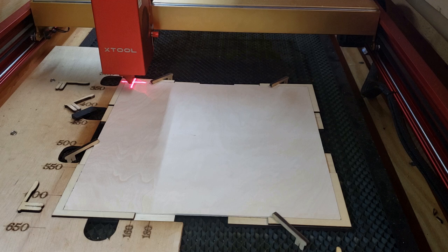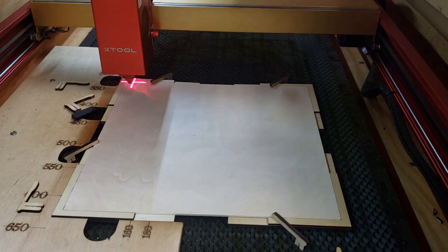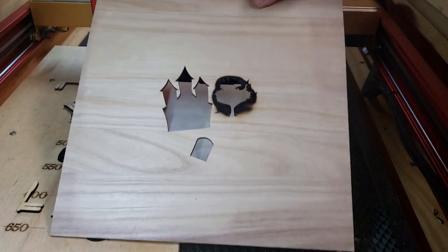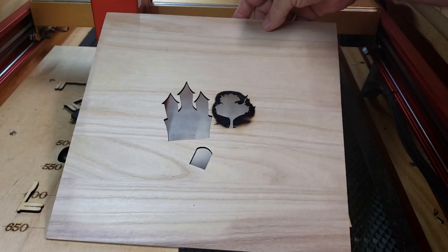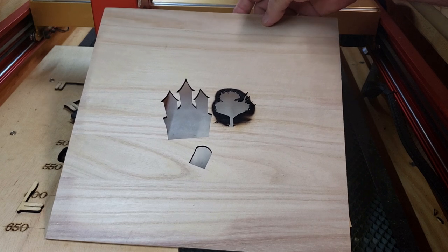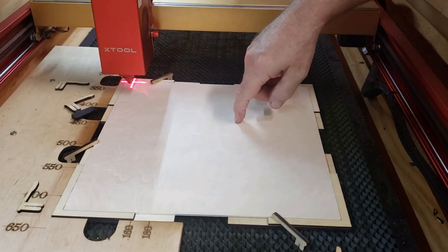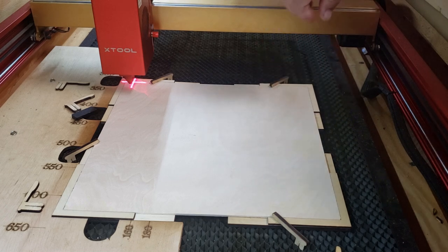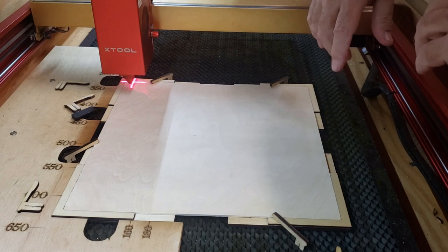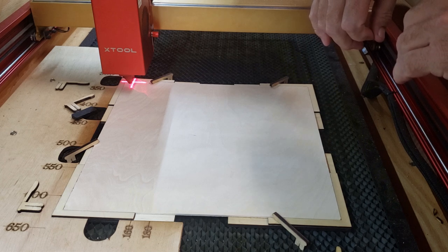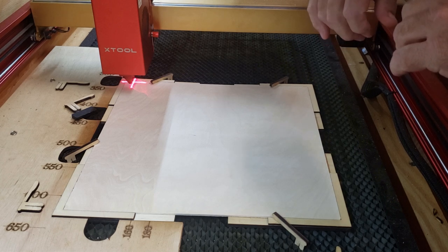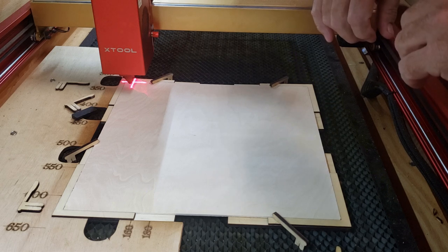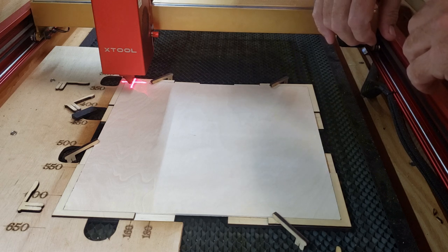Okay, we are framed up and ready, but this is the second time, because like I said, I intended to use this solid 3mm basswood, and it caught fire. So I changed over to a 3mm basswood plywood. The solid wood, I don't use it for customer products anyway, because it dents easily. It's kind of spongy. So be careful with it if you use it.